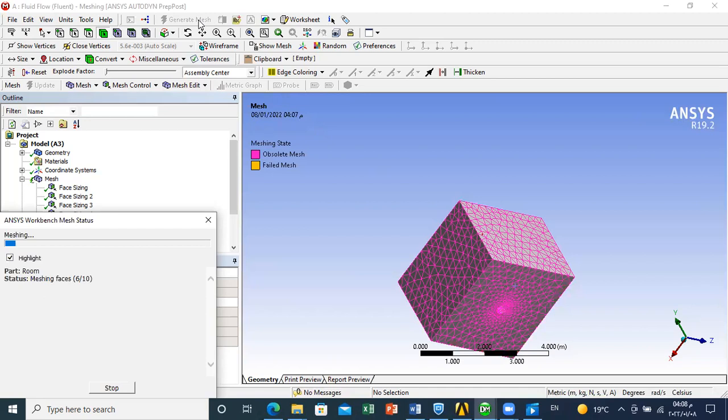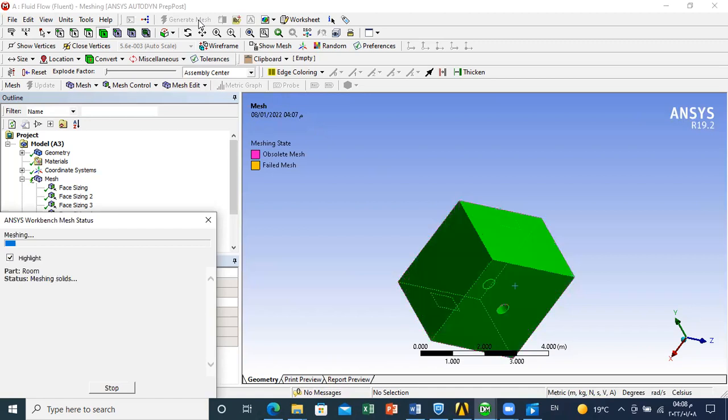In general, we have the largest aspect ratios near walls, because we'll see after that we'll do sizing at walls, and as we go far, we can go with larger elements. So this is why we expect that near walls the aspect ratio will be larger than other places. So this is another criterion you can look at when you look at your mesh quality.